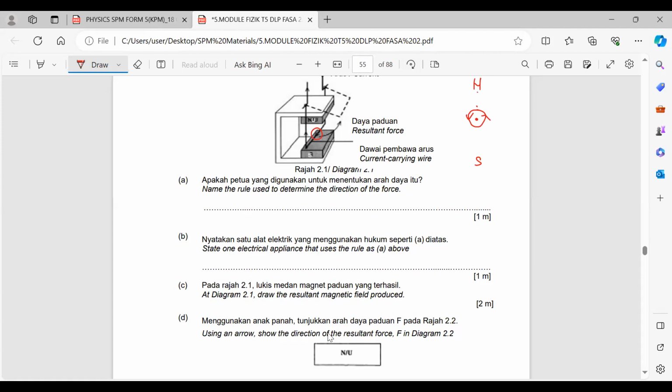Okay, fine. So now you can use your Fleming left-hand rule to identify the direction of the force. Current is flowing towards you, middle finger is pointing to your nose. Magnetic field is acting downward, not to the south. So I can see my force is to the right. Okay, force to the right.